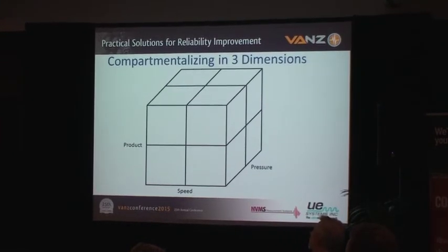But you can see that as we start compartmentalizing data, it becomes a more complex problem. But the good news is, with the condition monitoring and evaluation software that's available today, just about all of the suppliers in the market have the ability to compartmentalize the data based on machine operating state and the ability to generate and apply statistical alarms. That gives us a much better look at what's changing, so that we can focus on what's changing and decide for ourselves, is this a meaningful change or is this something that we can easily explain away?